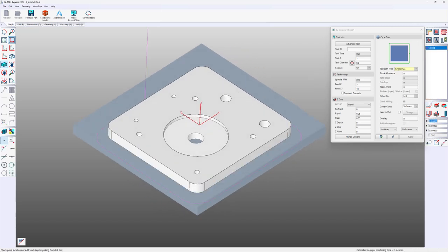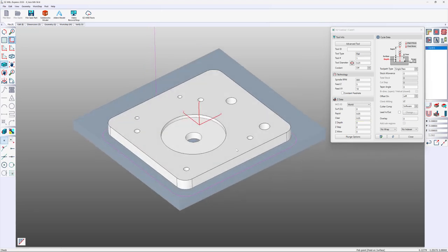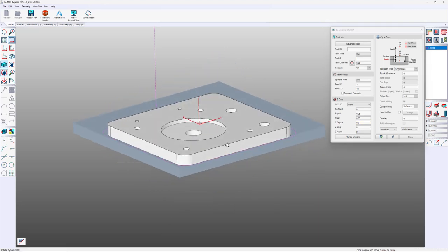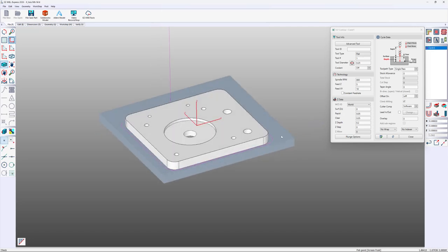So if I verify, let's change our cutter diameter to 1/4 of an inch. Depth is 0. Now because these surfaces are through with no floor, it gives us an additional depth so that we cut that completely. Let's leave a 50 thousandths height of our tabs, so I'll go with 0.2 inches. You can see that we're stopping. Now maybe 200 thousandths is a lot of material to take at once, so let's add a step of 50 thousandths.